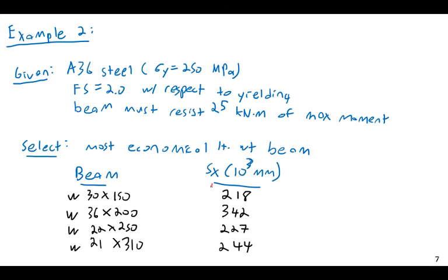However, we would have to be careful. The downside of this is that this is a very deep beam. This is a 30-inch deep beam. Often we can make a beam lighter, but in exchange we have to make it taller. It may be more structurally efficient, but in terms of a building, the beams essentially represent wasted space.